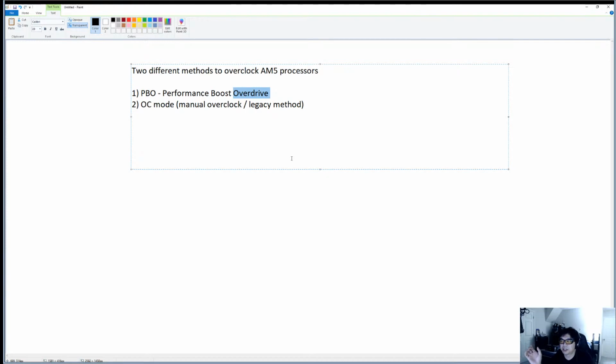Now again, it depends on the silicon, so there's a variance there. The silicon lottery determines whether or not you can hit certain clocks at specific voltage levels. But most of the time when you're overclocking, you become voltage limited, so you have to add more voltage.